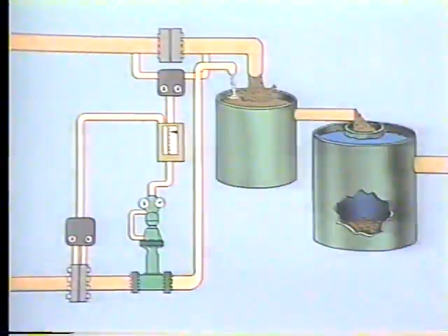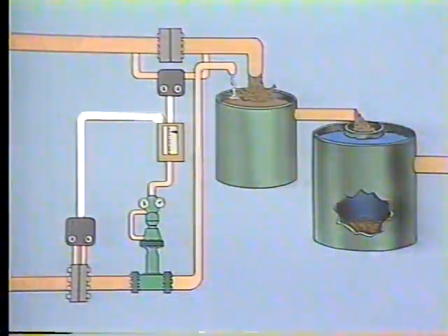To maintain the proper ratio of chemicals to wastewater, a ratio control system is used. So let's add a ratio control system to our water clarification process and see how it works. The control system for this example includes a flow transmitter to measure the flow of wastewater and a flow transmitter to measure the flow of chemical solution. Each of these transmitters provides an input to the ratio controller.